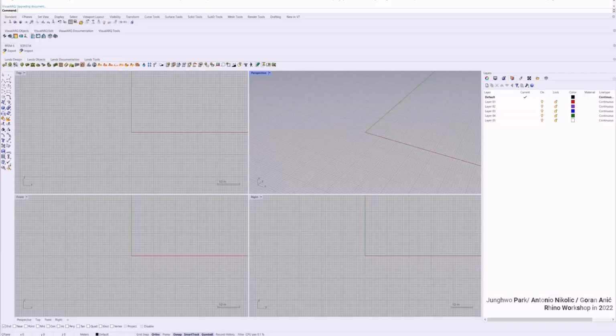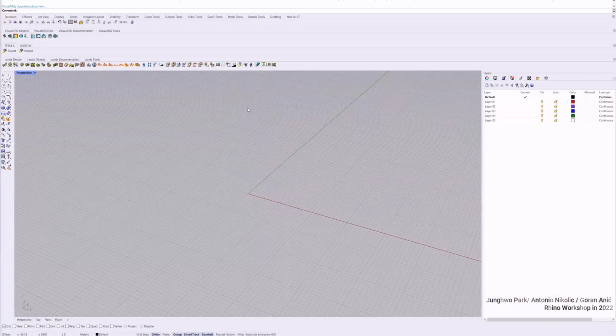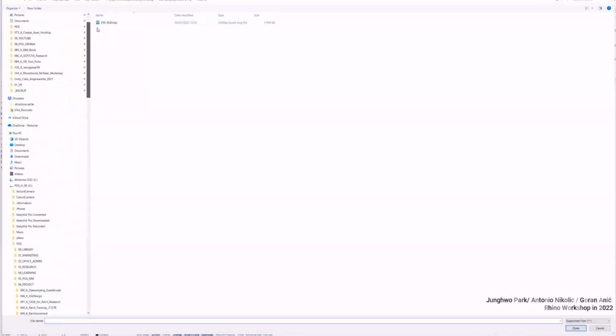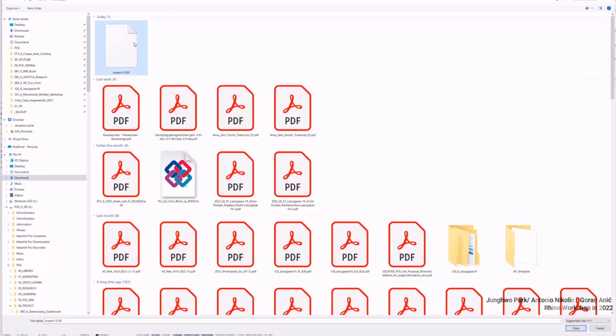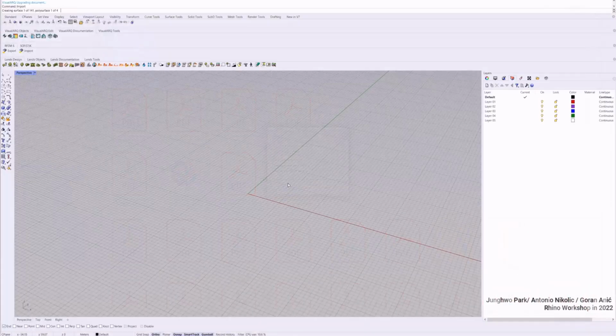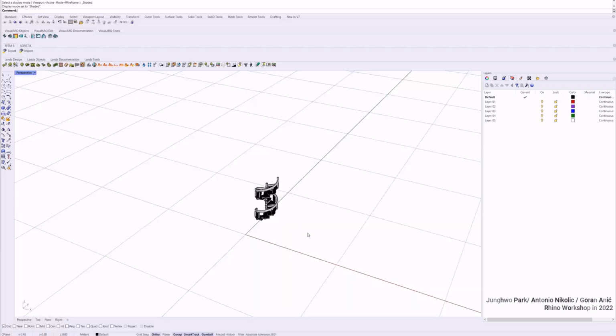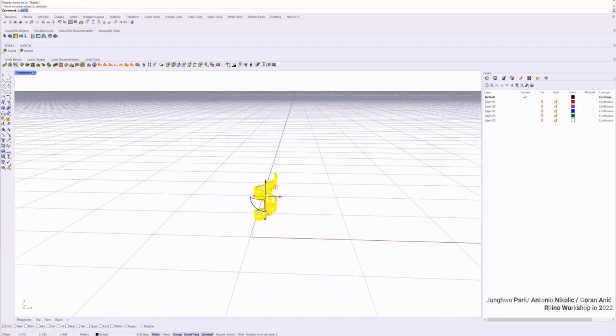And if I go now in here, let's import that step file. Then we'll bring it. So the Rhino model is in meters, it's millimeter. Scale input to match, yes. I don't think it's scaled correctly, so let me scale it up. I'll make it 1000 times bigger.